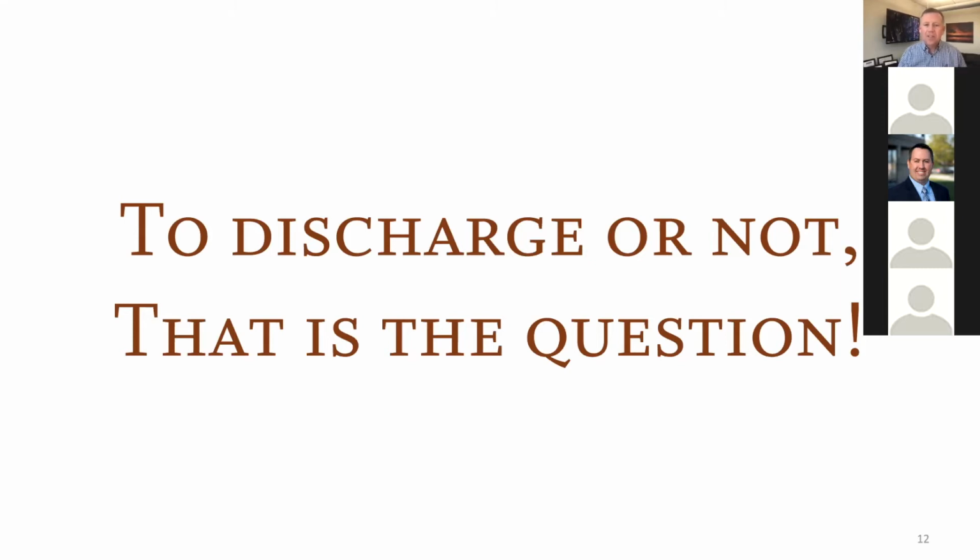Now, this is a big question because of a number of reasons. It's easy to not recirculate. It's easy to just discharge this water. Now, there are some downsides to discharging the water. One is we can look at that as, well, we're probably wasting a lot of water, particularly if it goes straight to the sewer system after being used in our splash pad. We live in a desert, and it's a very dry year, and so making that decision may have some negative side effects to it.